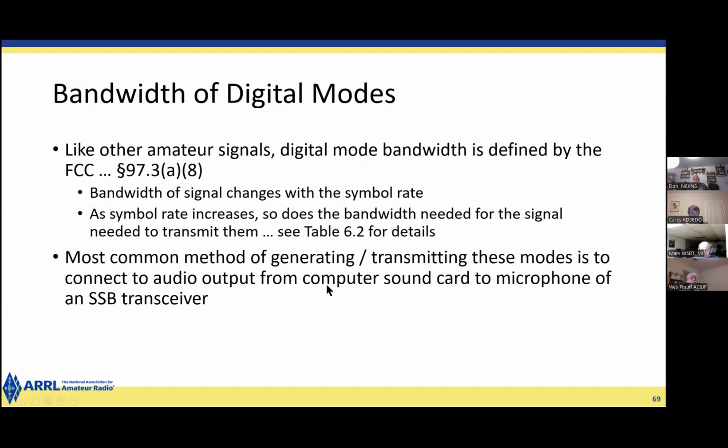The most common method for transmitting data modes is to connect an audio output from a computer sound card to the microphone input of an SSB transmitter.